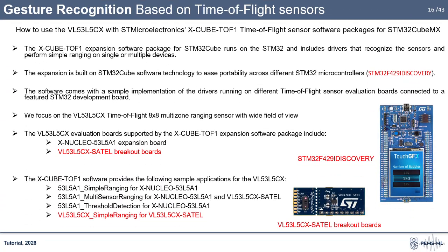To implement the system, we will use two interconnected boards, the VL53L5CX SATEL breakout board, which houses the VL53L5CX time-of-flight sensor, and the STM32F429 Discovery microcontroller platform, along with the corresponding software. ST Microelectronics provides a complete software ecosystem for their microcontrollers, which reduces development time and lowers the barrier to entry for complex sensor systems.